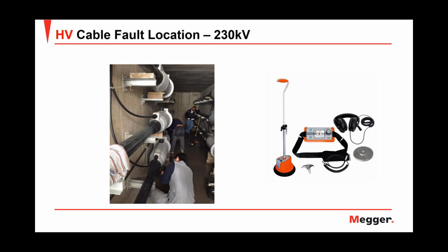Then, when I was done with the prelocation, I used the Digiphone, the pinpointer, to pinpoint the fault. And if you take in mind the place of concrete, the Digiphone did a wonderful job, because even under such conditions it was able to pinpoint the fault, and I confirmed where the fault was. That was in the second splice. So the guys have all the assurance to break down the concrete place and do the reparations, as you can see they are doing in this picture.